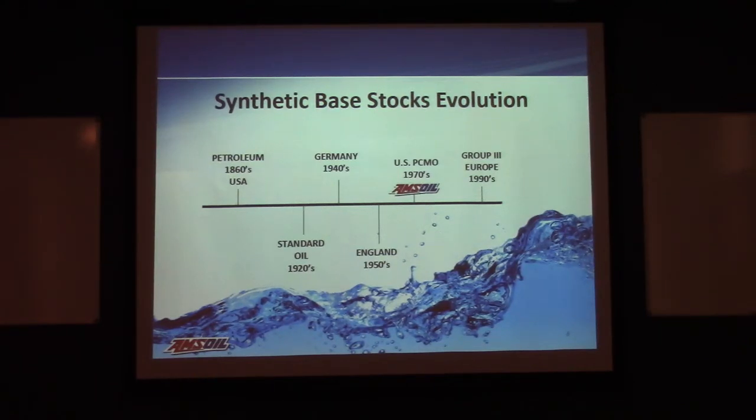In the 50s, in England, during the development of the jet engine, they ran into some real issues. They ran into issues of functionality at temperature extremes. At altitude, we're looking at sub-zero temperatures, minus 30, minus 40, minus 50 degrees Fahrenheit, okay? But they also looked at the temperatures at which many components within these jet engines were running. Very, very high, 500, 600, or 700 degrees Fahrenheit. I mean, these were extremes way beyond anything mineral oil could ever come near handling.